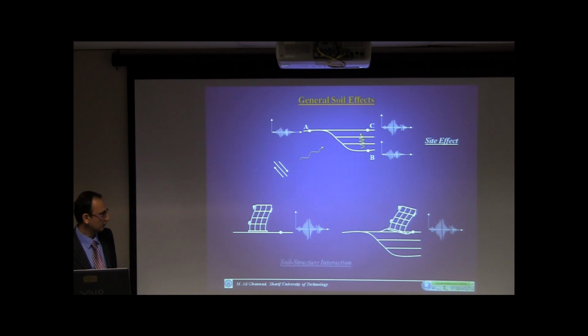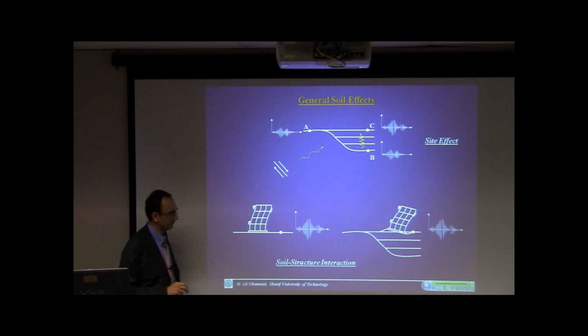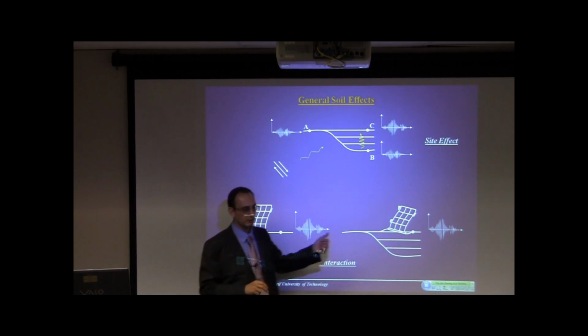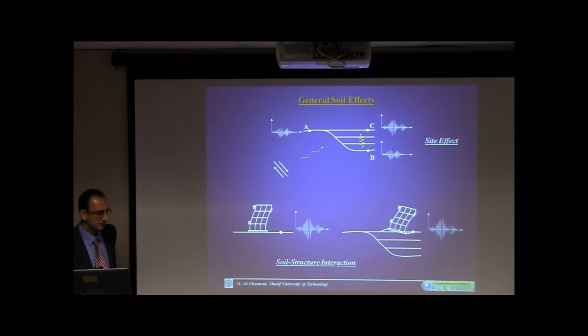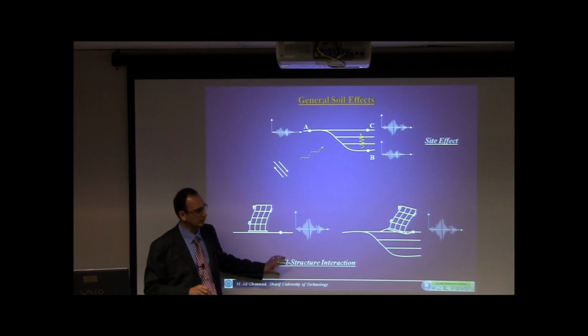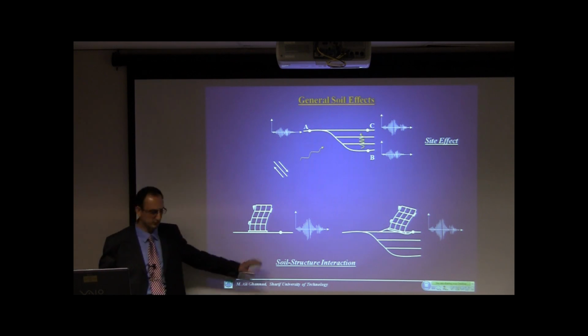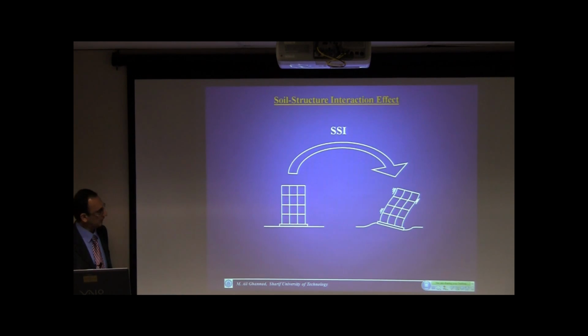And this is due to the soil structure interaction, because of the flexibility of the soil. The flexibility of the soil changes the response even to the same excitation. And this is the point that we are going to focus on in this part. Of course, the site effect is also known from the early years of earthquake engineering, but we are mainly going to focus on this one. So this aside, the soil structure interaction changes the response.